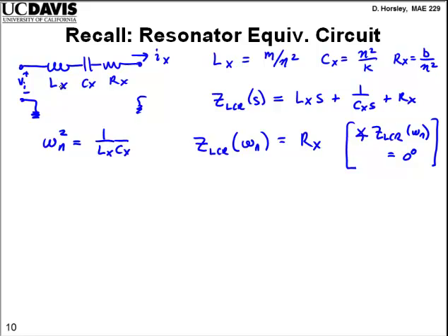And this is also, if you remember way back when I talked about mechanical equivalence, right? We said that at low frequencies, the system obeys Hooke's law, and so the spring dominates. And indeed, that's the same thing here. The C element represents the spring. So at low frequencies, this is dominated by Hooke's law. And then at high frequencies, it's the mass that dominates. And indeed, the mass is the inductance, right?